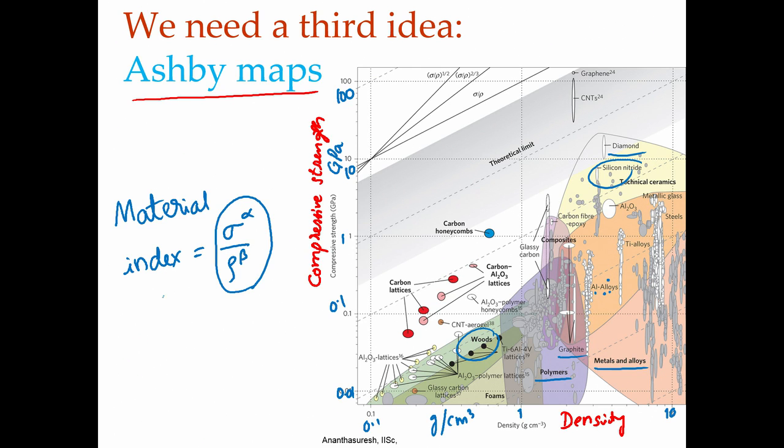So, I can write log sigma equal to beta log rho, and then it will be divided by alpha, right, and there could be some constant as well, depending on what all you have in the performance criterion. So, basically between log sigma and log rho, you have a linear relationship, you get a straight line.